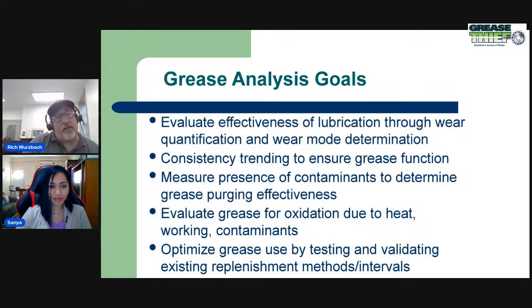So we talked about electric motors. We talked about the motor operated valves. And once you got those samples, now what becomes our goals for grease analysis? Well, we want to evaluate the effectiveness of lubrication through wear quantification and determining what wear mode is there, right? Where are the particles coming from? And a lot of that's through analytical ferrography to see what wear mode.